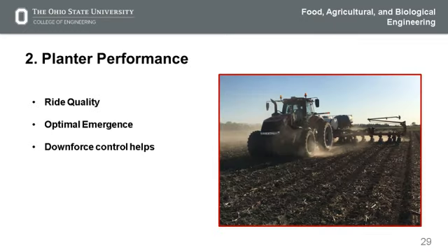One of the things that we did, we evaluated the effect of planter downforce on our strip till this past year, and we found that we've had a little bit better ride quality for our row units, and we really feel like that provides the best seed bed to plant into. So we've seen the opportunity for a little bit of planter performance increase there, and downforce definitely helps. If you're moving from field to field, your strips will change, and then obviously your downforce levels will be affected there.